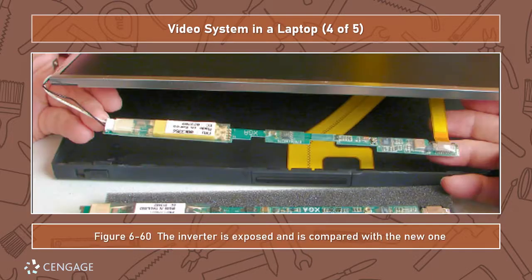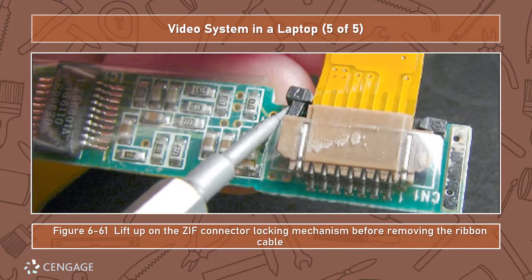So here we can see the exposed inverter. It's difficult to kind of see the bottom one, but the one at the top, you can see there's a little bit of burnout on one of those component chips. Here we can see the ribbon cable that's supposed to be holding that connector in place. So you would use the end of a flat screwdriver to just kind of push it up, and that little wedge is going to release the pressure on that ribbon contact so that it can slide out smoothly. Again, zero insertion force. So once the ribbon is in place, you lock that little tab. It's just going to press firmly but gently across the top.